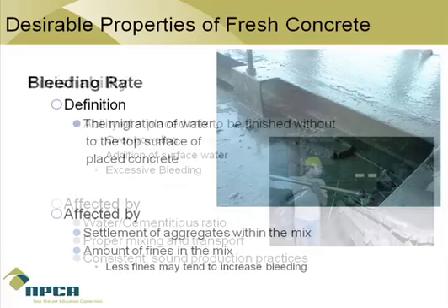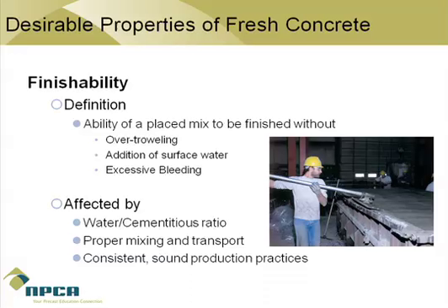When finishing concrete, it is important not to finish concrete while the bleed water is still moving to the surface. Finishing during this time will force the bleed water back into the concrete. This will weaken the concrete surface layer and may also cause scaling. For those of you who have had the opportunity to finish concrete, you know that it is an art more than a science. It can also be much more difficult than it looks, depending on the concrete mix that you're working with. You need to take care not to perform the final finishing before the bleed water has had an opportunity to evaporate.